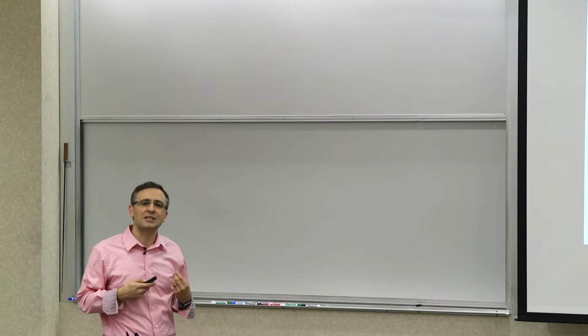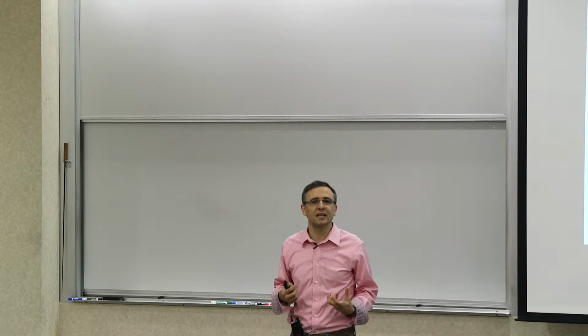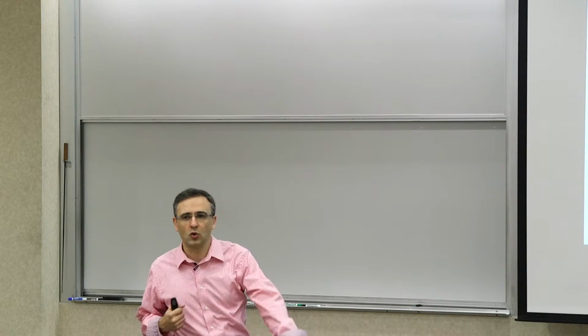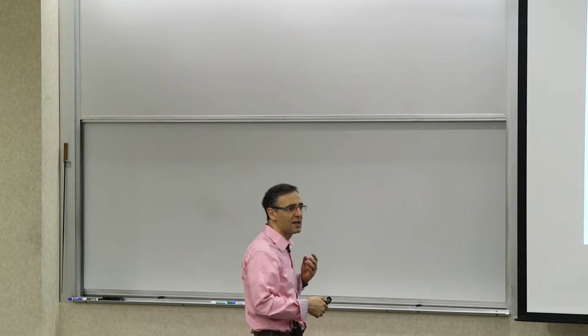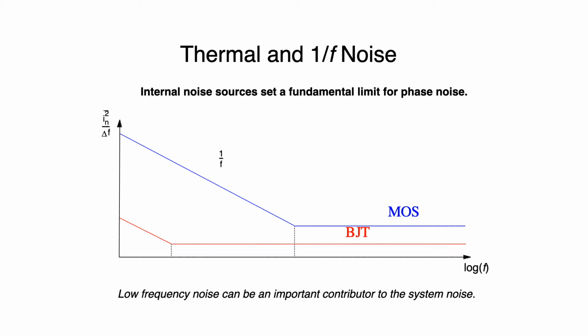Now, what is causing this? There are several different things that can cause frequency instability. Some of them are what we call the intrinsic noise sources. We talked about noise sources before. There is thermal noise in the MOSFET, the shot noise in the bipolar transistor, the flicker noise of the device. And these can have different profiles, right? For example, the spectrum of the noise itself can have a 1 over f region due to flicker noise, and then a flat region due to white noise, or thermal noise, which we approximate as white noise in the frequencies of interest, right? So they have a spectrum like this, and each one of them has its own corner frequency, omega 1 over f, or f1 over f, the 1 over f corner.